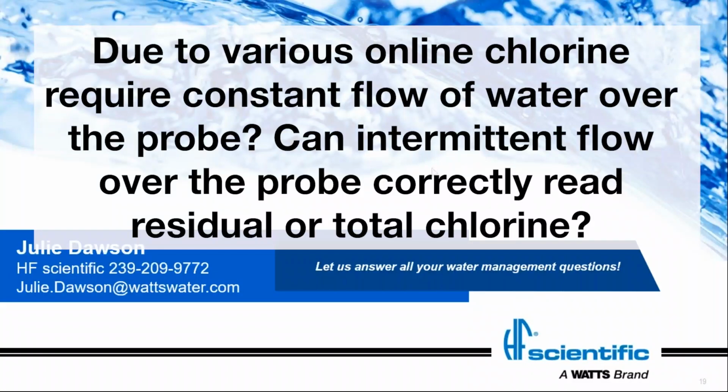So intermittent flow over the probe generally causes problems. And if you were to turn it off and back on, you would need to go out and do verification of both your pH probe, right? Because we're talking about an amperometric in this case, or are we talking about the ISE method? So for amperometric, we would need to go out and do verification that the probes were both working, because dry sample can kill those probes, and they are very flow dependent.